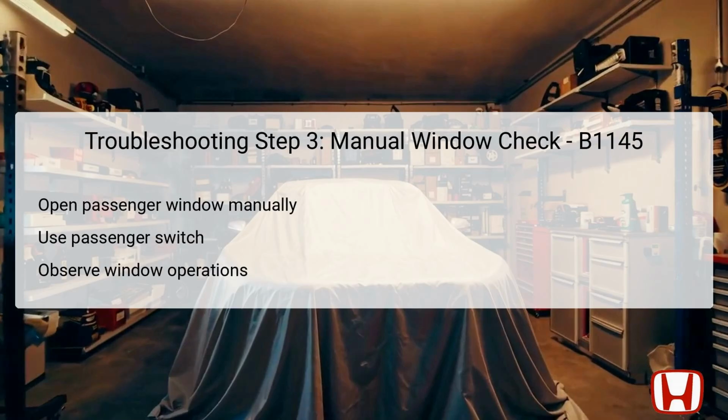In the third troubleshooting step, manually operate the front passenger's power window using the passenger window switch. This step is essential to assess whether the power window system responds correctly when operated manually. By doing so, you can observe the movements and see if the window operates smoothly or if any abnormalities occur.